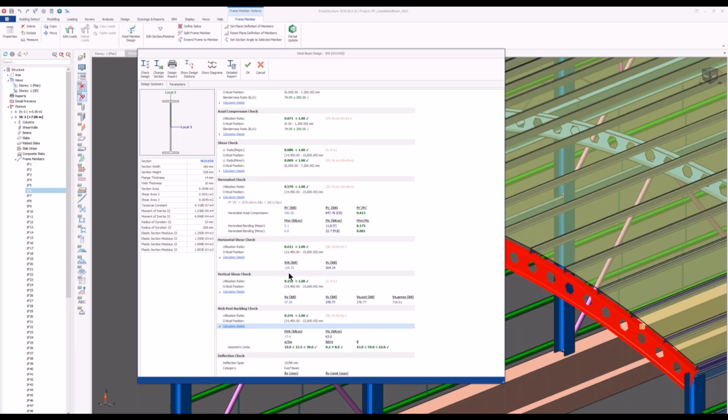Because when we create some openings, we will have two T sections at the top and bottom, and the entire castellated beam will start to act like a Vierendeel truss.